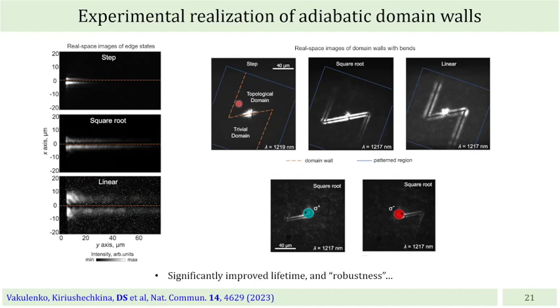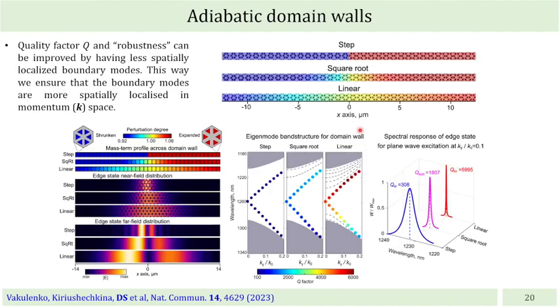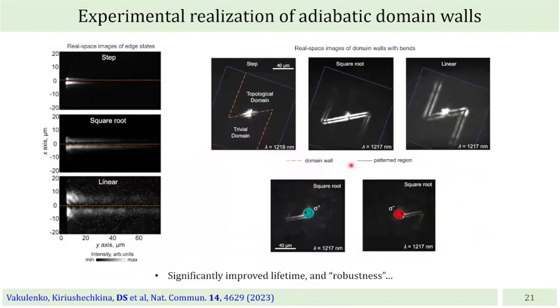To demonstrate this, we fabricated comparable structures. Previously, the mode doesn't even reach the corner. For adiabatic interfaces, it reaches it and turns. However, this is probably not the way to confine light if this is required for enhanced light-matter interactions. The other interesting feature associated with this adiabatic interface is the occurrence of additional doubly degenerate waveguiding modes within the bandgap. They're shown here with dashed lines.